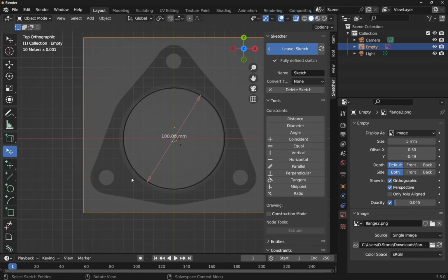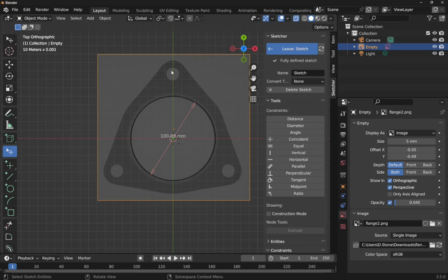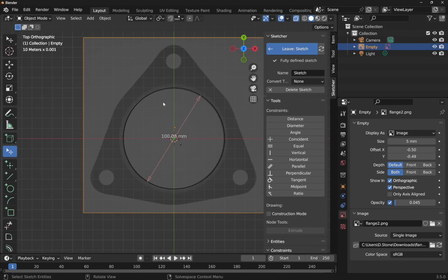So we're going to take it stage by stage, making it simple. This sketch is symmetrical. So I can do one of two things. I can basically sketch the whole of this, or I can sketch one side and mirror it. I'm going to go for the whole of it. So what that allows us is to practice our tracing skills, because we're going to be repeating circles, repeating arcs, and repeating lines that connect up those arcs, and the tangency constraint, etc.